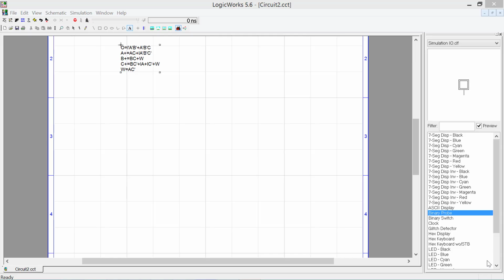Let's build the circuit for the countdown from 5 alarm. We have copied over the truth table equations that we optimized with K-maps over to our simulator here. So now we don't have to go back and forth between the notes that were taken in the previous program. Let's just start implementing the state machine directly. We have A plus, B plus, and C plus. So we have 3 state bits, n equals 3.